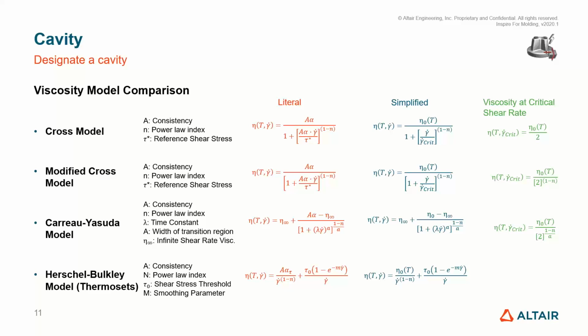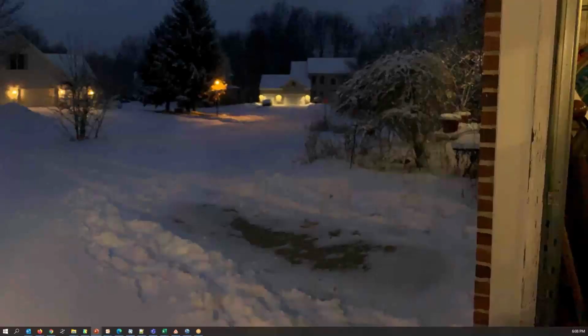As I go faster and faster with water, I can just draw a line and say, okay, I want to know what the pressure drop is as I fill this thing at whatever speed. I've got one viscosity, right? And so the pressure is a linear extrapolation versus that flow speed. In this case, not linear. It kind of trails off and starts to look almost asymptotic. So, something to keep in mind.